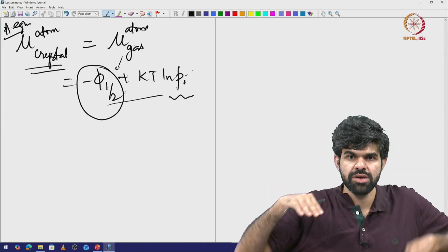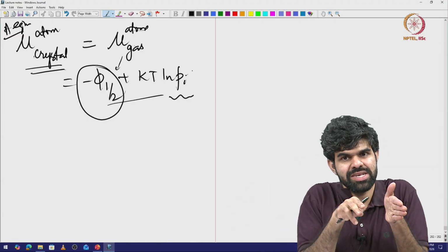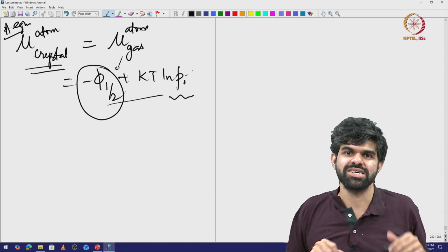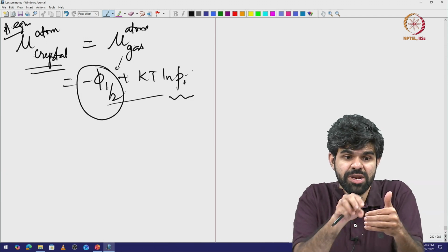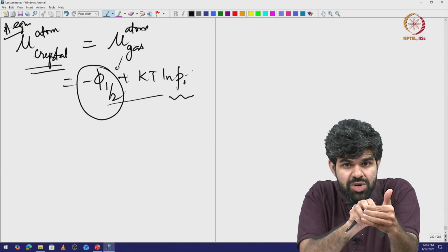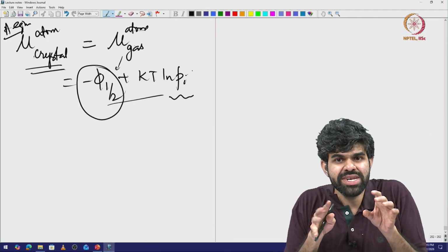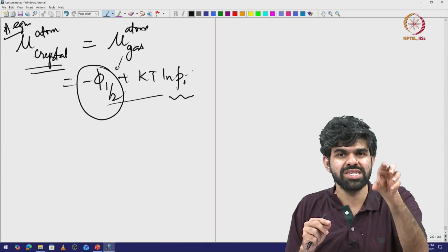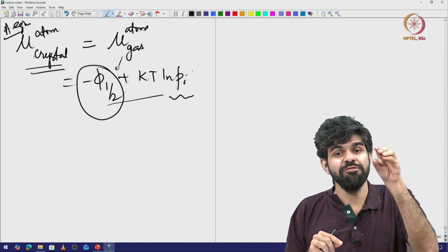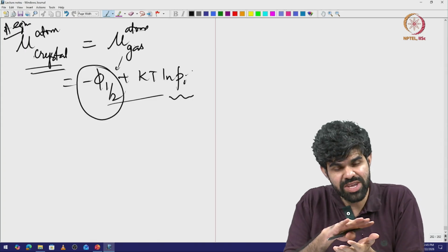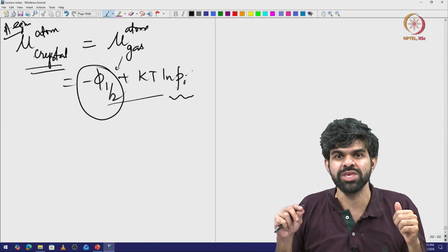So there is a terrace like this, they can come like this, hit the terrace, go here and then hit another terrace, and then they can get stuck there. Similarly, it is easy for that atom to come out and go out into the gas phase. So it is okay to consider that position as a special position, and if I have the complete growth happening through only those positions, then that's a very smooth flow, that's called step flow growth.